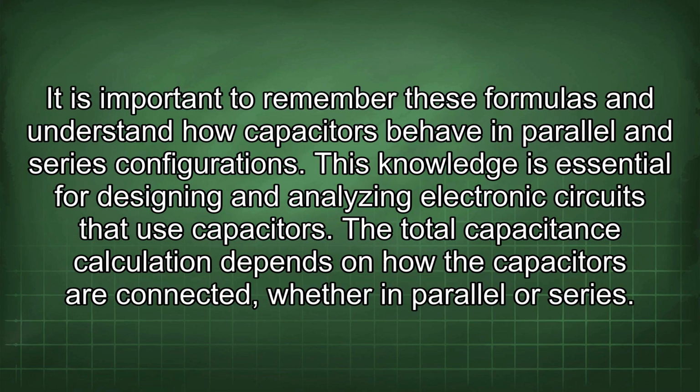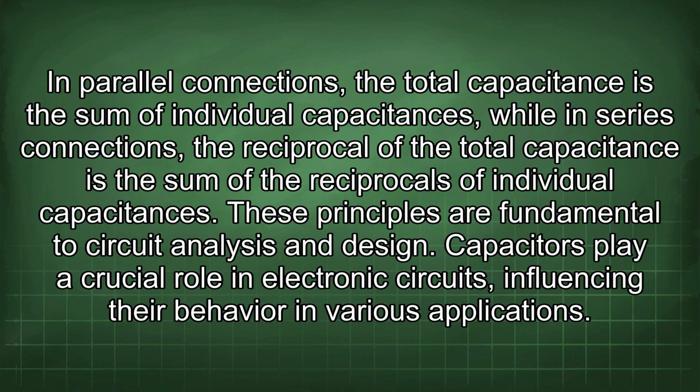It is important to remember these formulas and understand how capacitors behave in parallel and series configurations. This knowledge is essential for designing and analyzing electronic circuits that use capacitors. The total capacitance calculation depends on how the capacitors are connected, whether in parallel or series. In parallel connections, the total capacitance is the sum of individual capacitances, while in series connections, the reciprocal of the total capacitance is the sum of the reciprocals of individual capacitances. These principles are fundamental to circuit analysis and design.